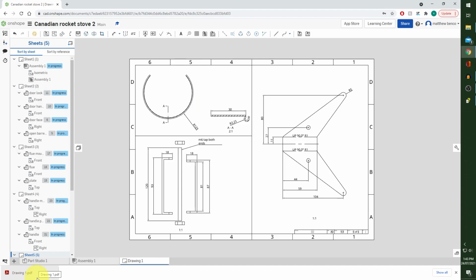Now it is set to A3, so make sure that you are using a printer that is A3. Make sure that when you're printing, you select the option which doesn't shrink it or change it at all. Or you can shrink it and put it down into A4, but if you print it in A4, it's not going to be to scale, so you just have to watch out for that. You're all done. Good job.